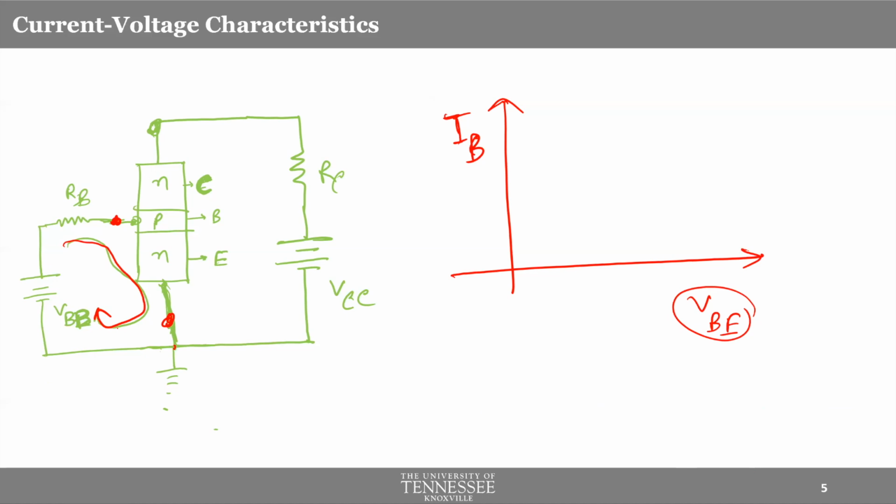Okay. Now, interesting thing, just forget about the collector here. Just look at this portion of the BJT. Isn't that a simple PN junction? So when I talk about base emitter voltage, I'm applying a voltage across this PN junction, and depending on whether it's forward biased or reverse biased, we will have characteristics which are similar to the diode, right? And remember, we are looking at a forward active mode. Forward active mode means the base emitter junction is forward biased. So the VBE that we are looking at is given in a way that this PN junction is forward biased.